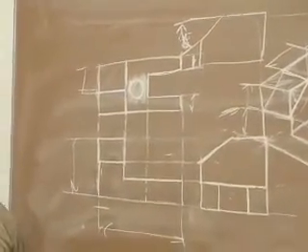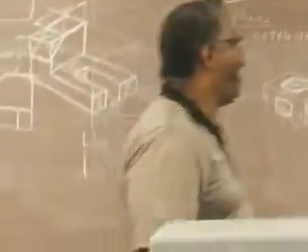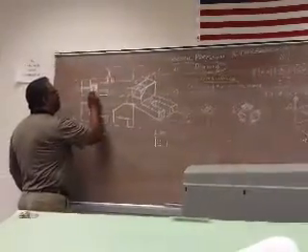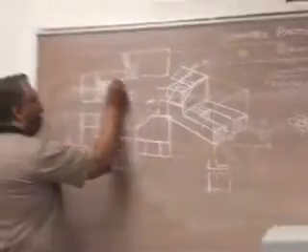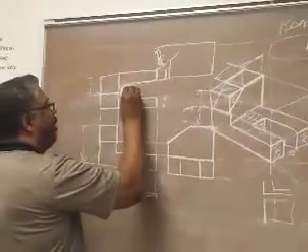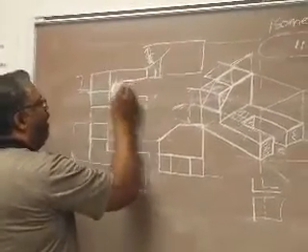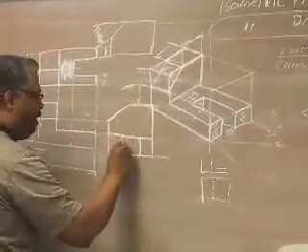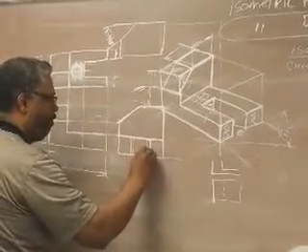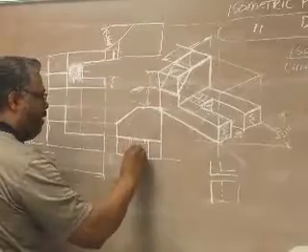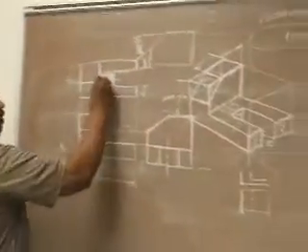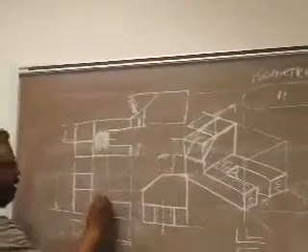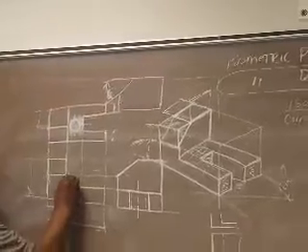Do we put hidden lines on the side view? Now, if I had a hole in the object, it produces hidden lines. So now I've got a center line, so I'll show the center line of my hole. And then I've got the hidden line, so let's say this is centered in there. Then I'll pick up a hidden line here for the diameter of my hole. I'll pick up a center line there to show the axis of my hole. I'll come here, pick up a hidden line here, and a hidden line here, and then the axis of my hole.